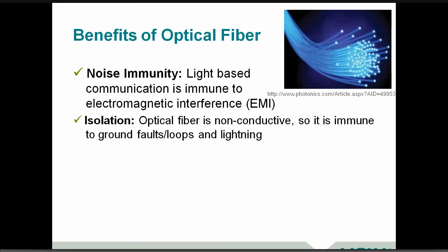And some of you folks, being engineers working with maybe other signals like serial ports, a lot of times if you're working with serial ports, grounding is really important, and ground loops can be a big problem. And you probably would choose products that have optical isolation, utilizing an opto-isolator, which is a little mini fiber optic media converter on a chip that's within the products to do this type of thing. This gives you total isolation from ground loops, ground faults, and even lightning.